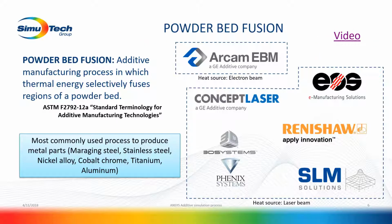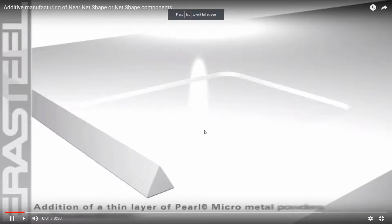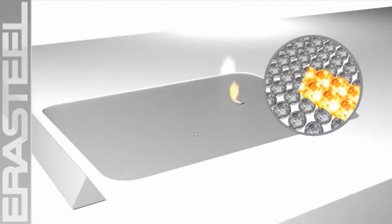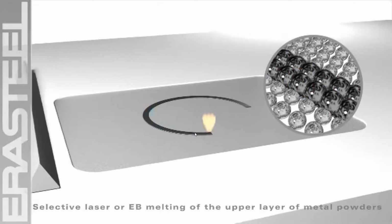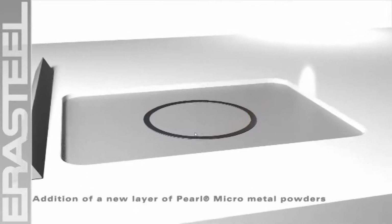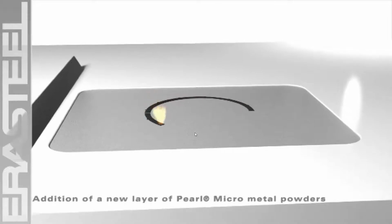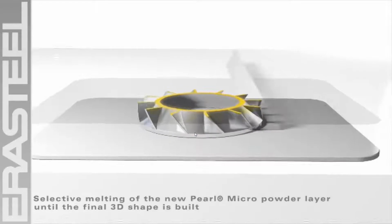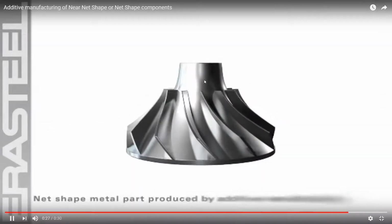So to this end, I have this little video for you. So we start by applying a thin layer of metallic powder, and then a laser comes and selectively fuses the metallic powder at a specific area. Then we apply another layer of powder, and the process goes on and on again, in a way that we can print a part directly from 3D model data.